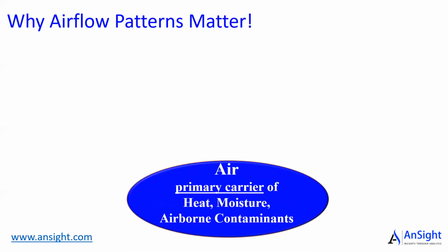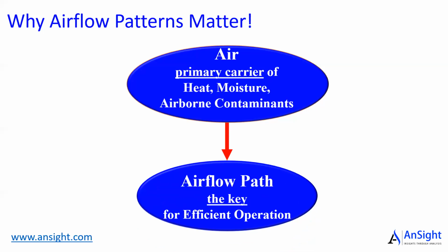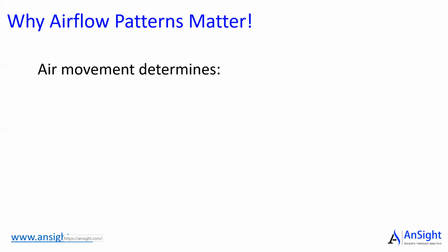So why does airflow matter? Air is the primary carrier of heat, moisture, and all airborne contaminants, and therefore understanding the flow path of air is key. It's key to your ventilation, it's key to how clean your space is, it's key to your thermal comfort, and it is key to your health and well-being and productivity. So that's why airflow patterns play an important role.